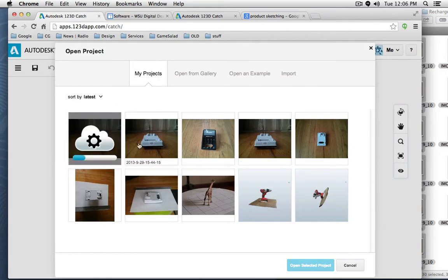You see here, I did various tests with small variations. And again, here, for example, you see I did captures on a white sheet, which worked okay, but sometimes the problem is if my object is white and the background is white, the scan can result in pieces blending together. When I draw something onto a white sheet, I can separate my background from my subject matter or my object. That will then help the software to understand what is a flat plane and where is actually an object to digitize.